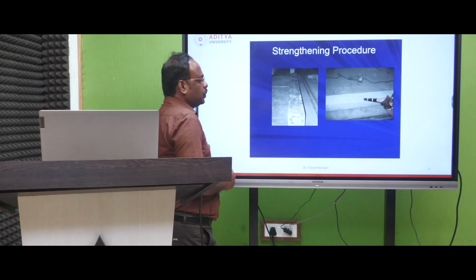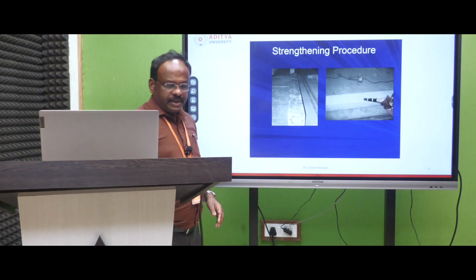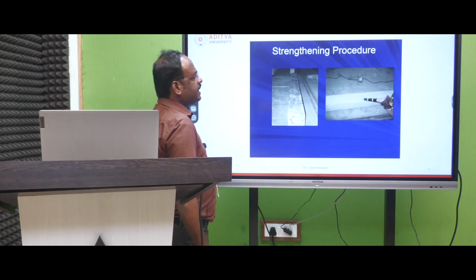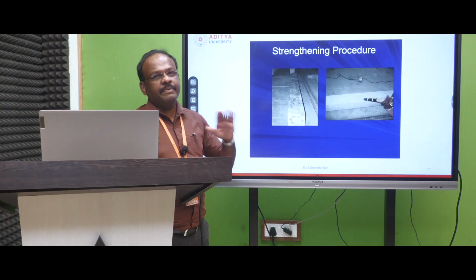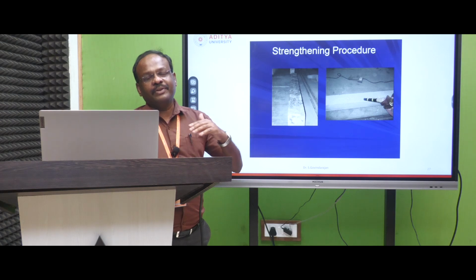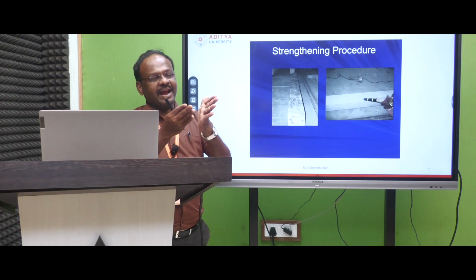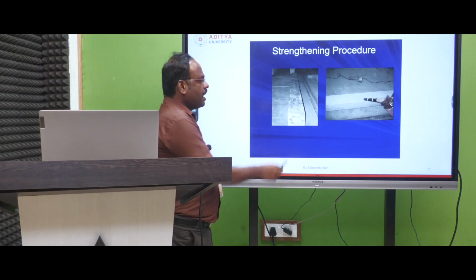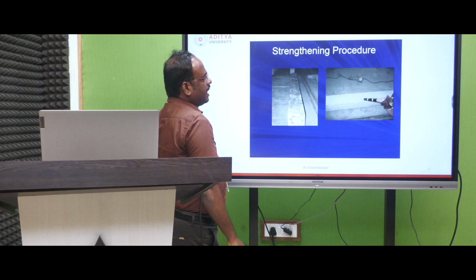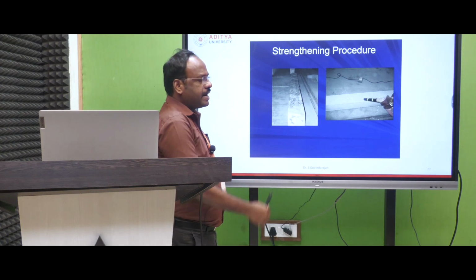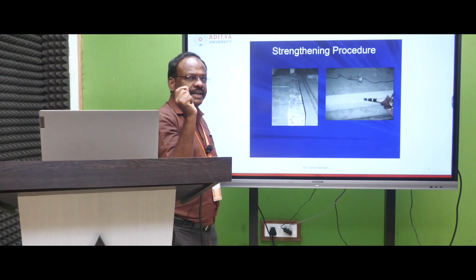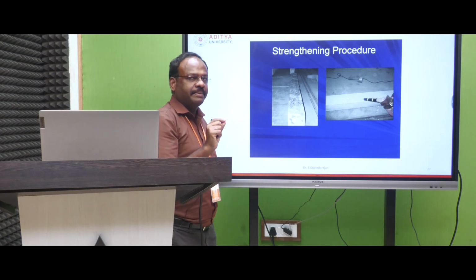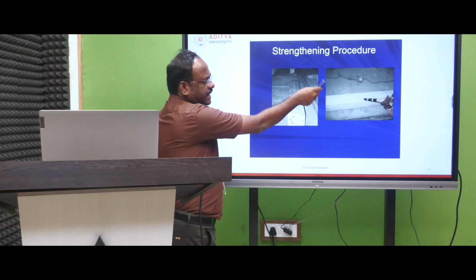First of all, what I am going to do is on the bottom side of the beam, here this is the bottom side, and these are the 2 sides, right? On these, first I want to do chipping, right? The surface will be in rough condition, not smooth. If you make it smooth, then fiber and concrete will not bond, right? That is the purpose. So I do chipping on all sides, and after that I use an air blower and remove all the dust inside the gaps, right? Because I use chipping, surely dust will be present inside. So I remove all that dust using the air blower.